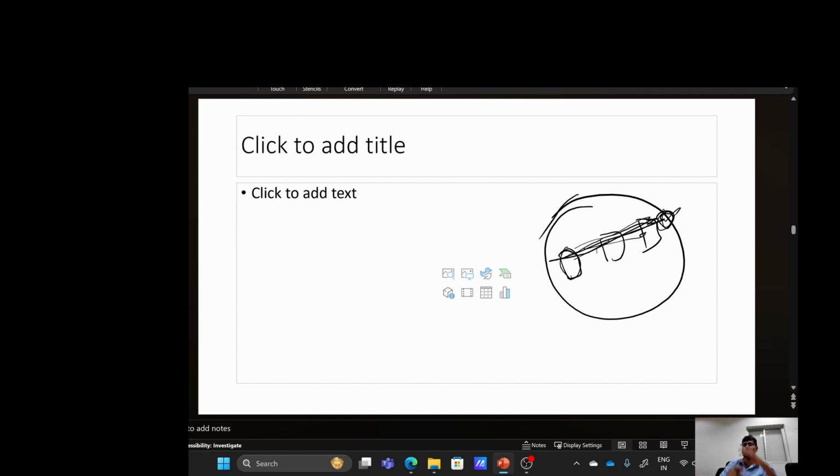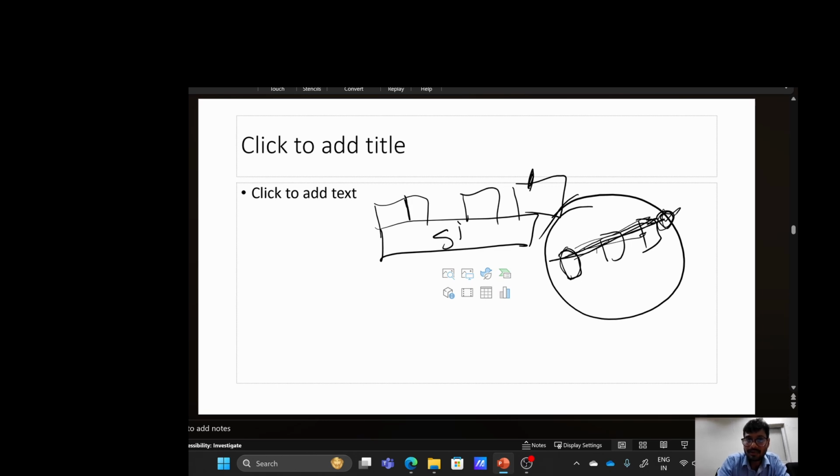So there will be a kind of SiO2, and there will be some steps. In this case this is silicon, and over this there will be steps. But you want to connect this one with this one. So how will you connect that? You need to do a conformal deposition. So there will be metal at this position, and metal at this position, which is connecting this.